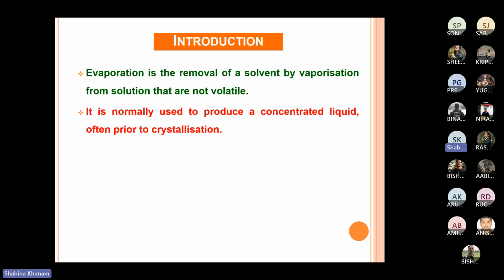And if I say that it is used prior to crystallization, you understand crystallization, right? It basically works on supersaturation conditions and is used to prepare crystals out of slurry. The formation of crystals requires a slurry of thick concentration, and that thicker concentration we get from the evaporator. So usually in chemical processes, the evaporator is used before crystallization. Okay, so that you understand.